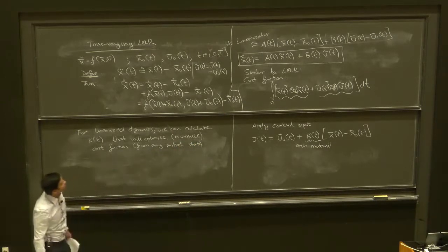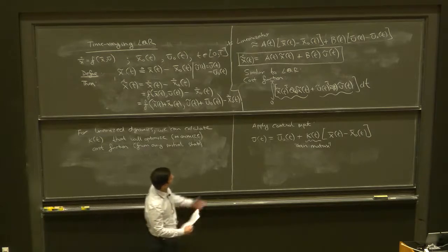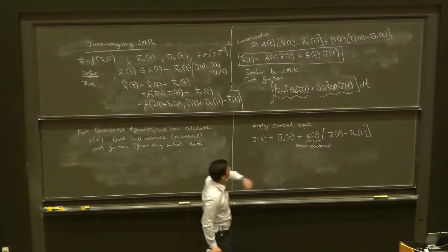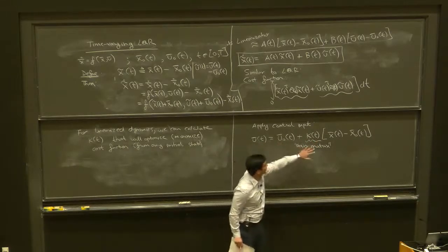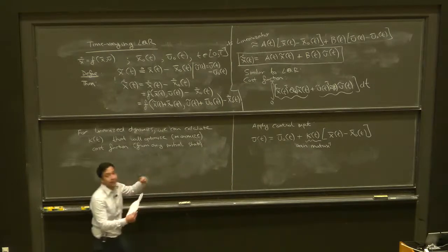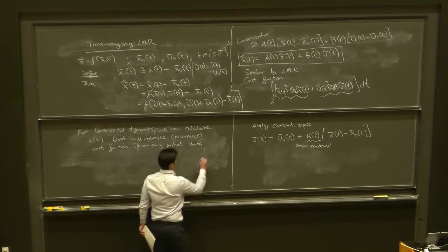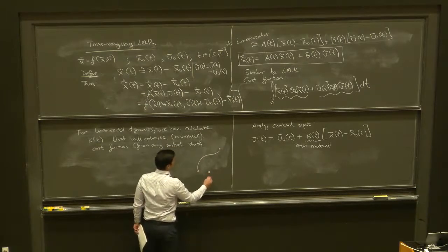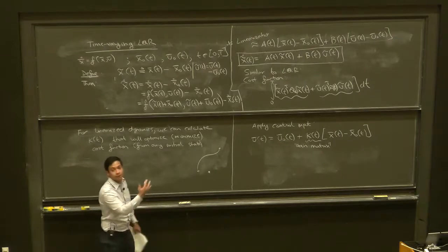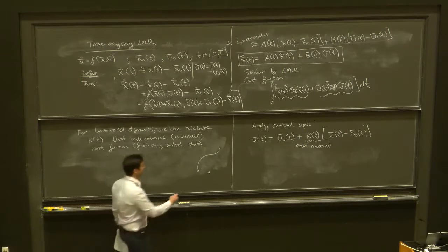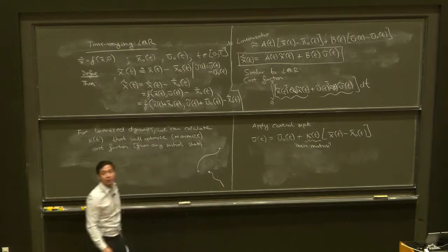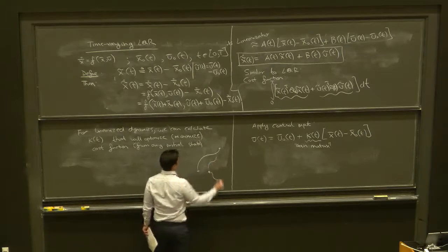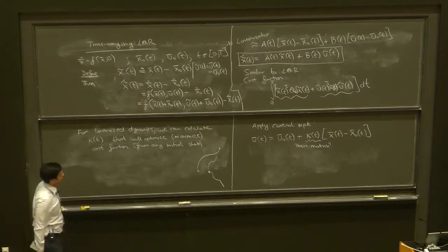So yeah, the way to think about this is if you choose some particular values for this matrix, this gain matrix, that fixes your feedback controller. You can apply that feedback controller, so let's say this was the trajectory again. From any initial state, wherever you start off, you can apply this feedback controller. It's going to do something, right? If you just make up random numbers, it might do this, not even get you anywhere close to the trajectory you want to be at. If you choose a good feedback controller, it will roughly get you back to the desired state.